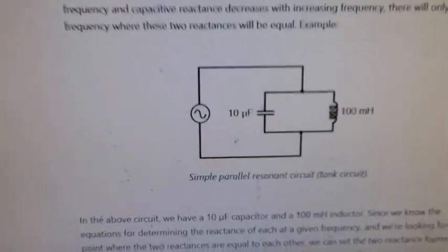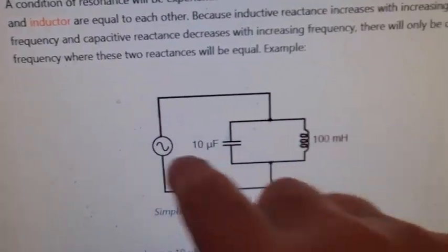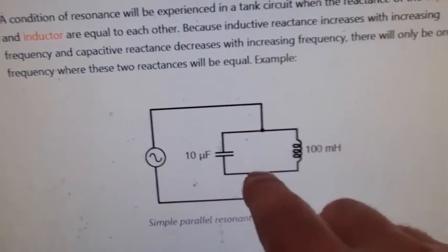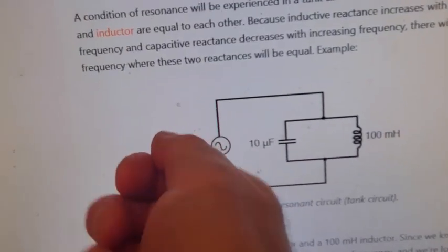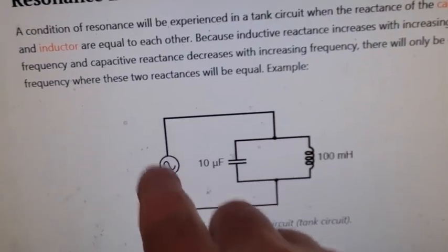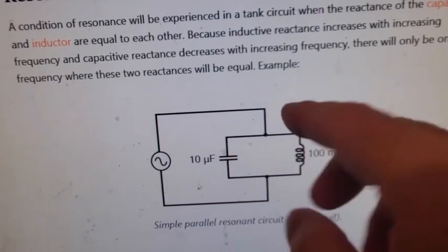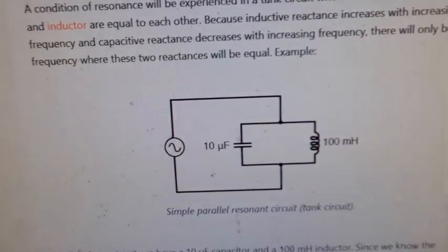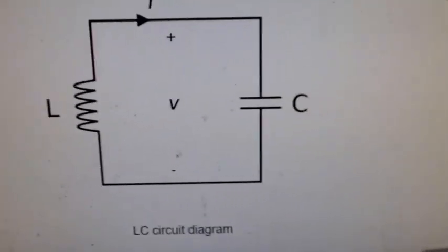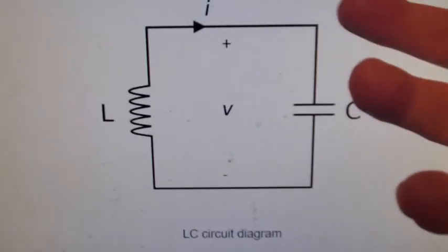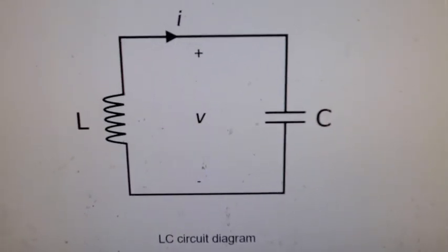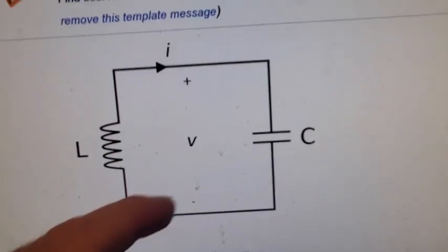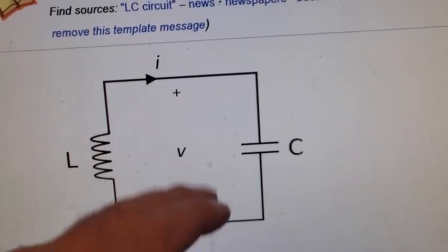LC. Not to get off topic, but if you go to a setup like this where you have an alternating current going into something, here you would want to adjust the alternating current to where it's going in at the same rate that this process is going on. So you would be adjusting it to the resonant frequency. But when you have something like this where you just discharge the cap, it just goes at the resonant frequency. There's nothing to do. That's where it goes. And then the question is, do you want to interrupt that process at different points along the resonant frequency?